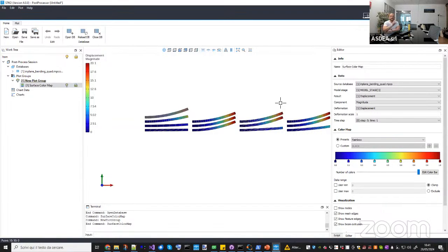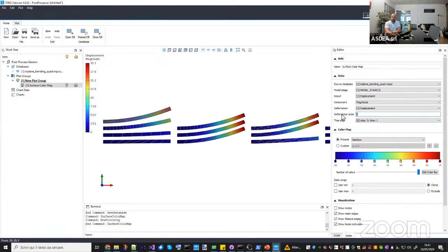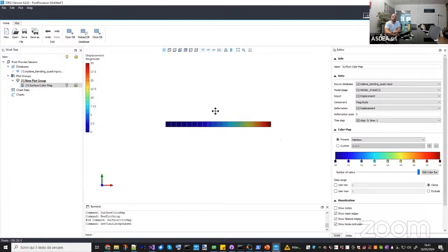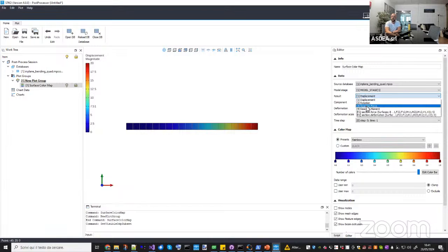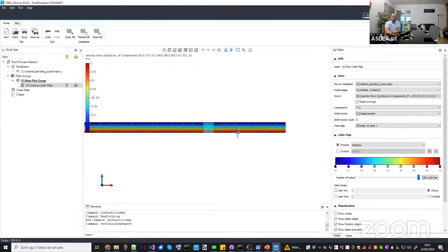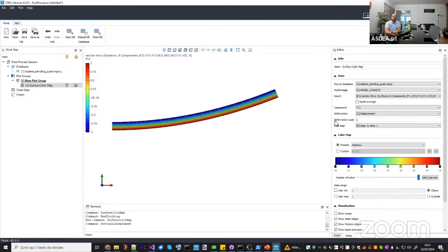Now the displacement, the exact solution for the displacement should be 20, okay? Now, just to show you the exact solution, I will show you this one, okay? Which is the ASDShellQ4. I isolated it for a bit. The exact solution should be exactly 20, okay? Given the shape of this one. If you take a beam, you apply a bending moment like that, you will see that this one is the exact solution. And if you look at the stresses in the x direction, it is exactly +1 at the bottom and -1 at the top, okay? Because it is bending in the upward direction.